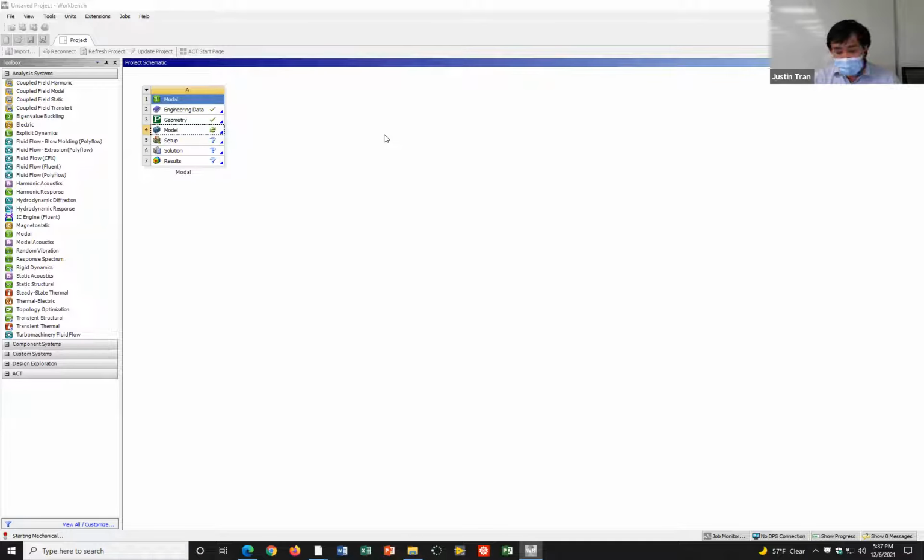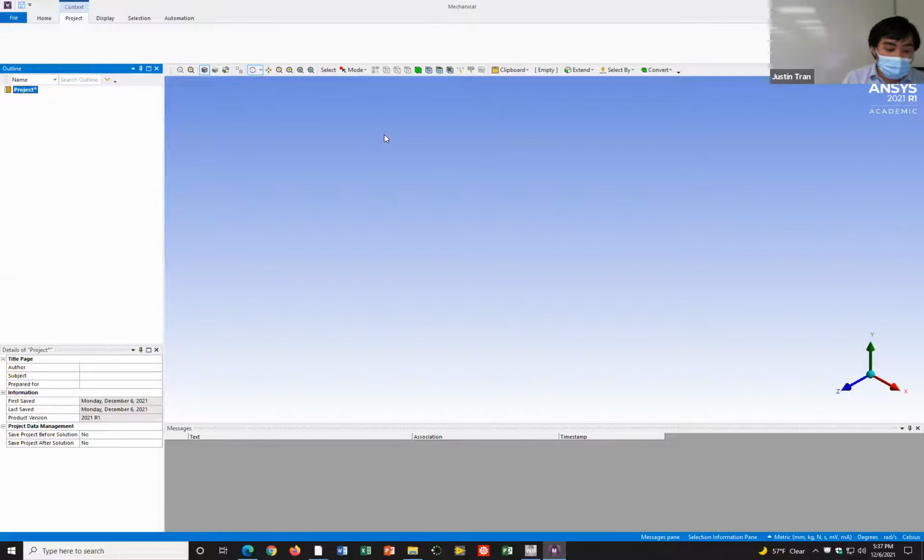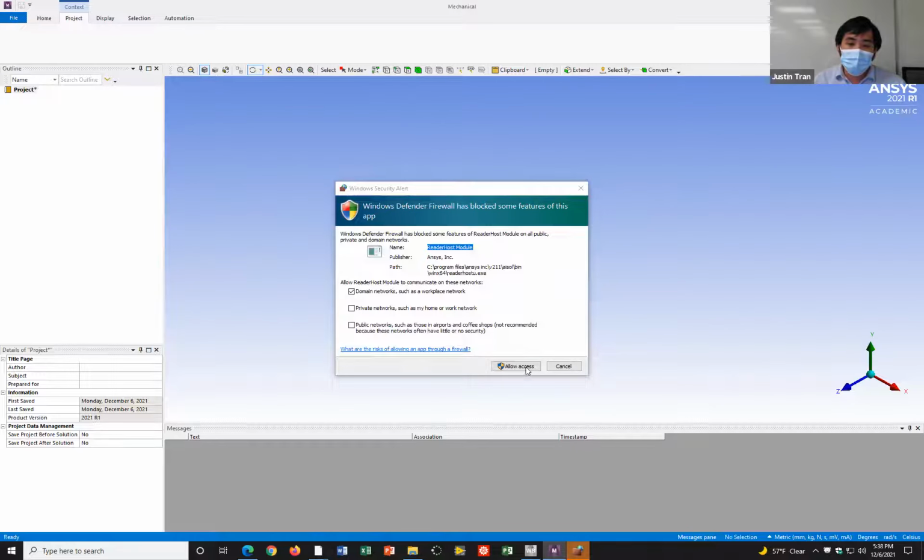All right. The first thing we're going to do is use modal analysis to find out what the natural frequencies are. This is exactly the same as Ansys Activity 7. So no different there. But it's going to be important to know what the natural frequencies are, because it's going to help us interpret the harmonic system response better. Okay.